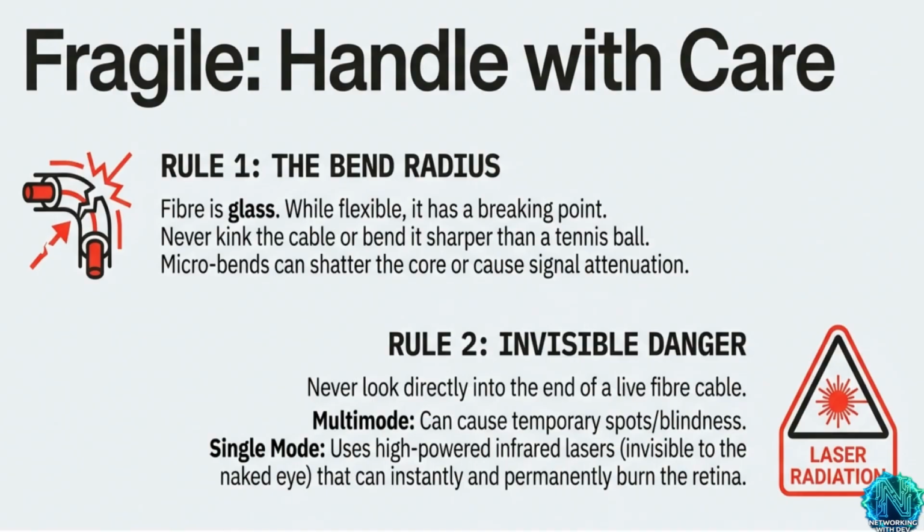Rule number 2 is about the invisible danger. You must never look directly into the end of a live fiber cable. While multi-mode can cause temporary blindness, single mode uses high-powered infrared lasers that are completely invisible to the naked eye. These lasers can instantly and permanently burn your retina before you even realize anything is wrong. Treat every fiber cable as if it is live and dangerous.